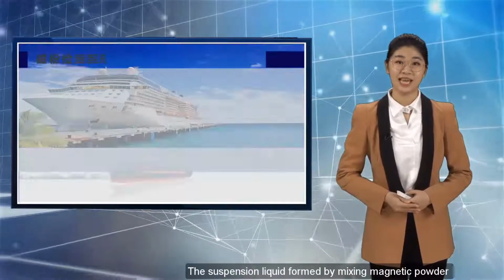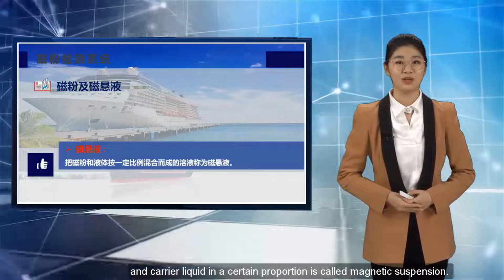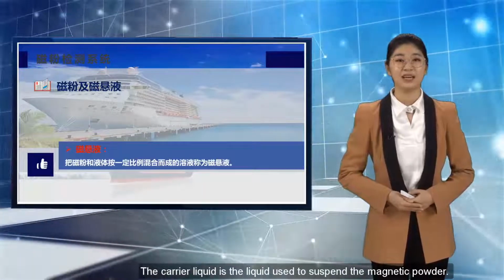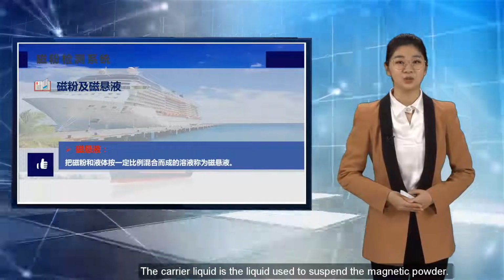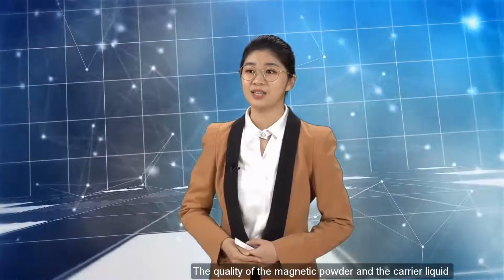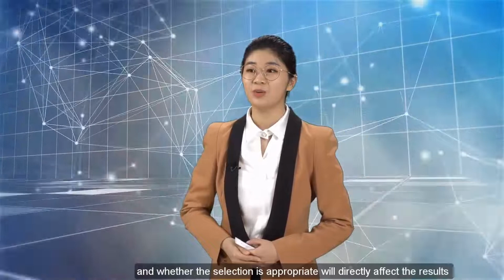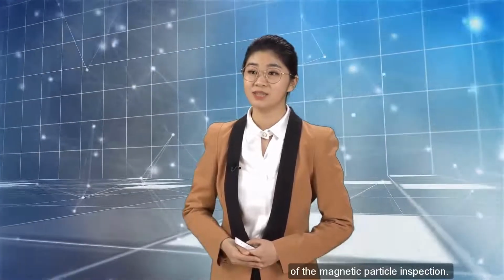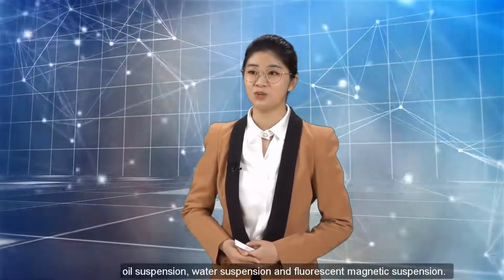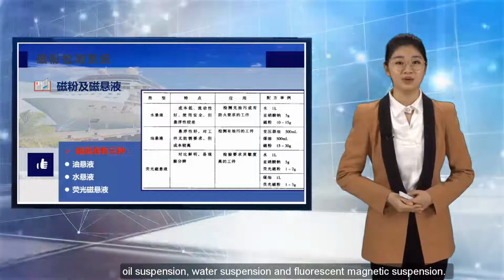The suspension liquid formed by mixing magnetic powder and carrier liquid in a certain proportion is called magnetic suspension. The carrier liquid is the liquid used to suspend the magnetic powder. The quality of the magnetic powder and the carrier liquid and whether the selection is appropriate will directly affect the results of the magnetic particle inspection. There are three types of magnetic suspensions: oil suspension, water suspension, and fluorescent magnetic suspension.